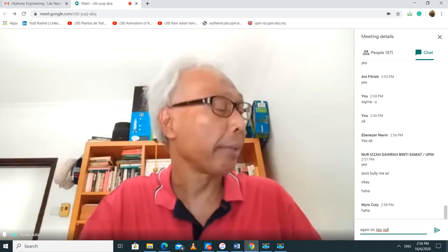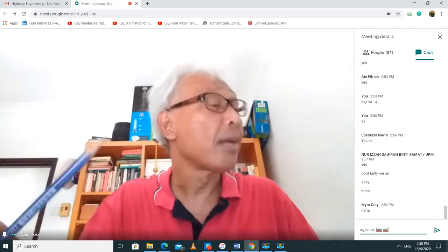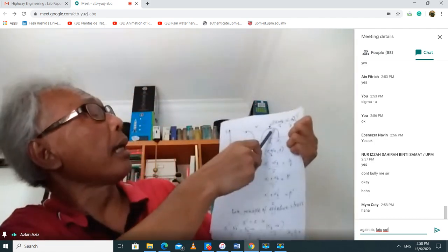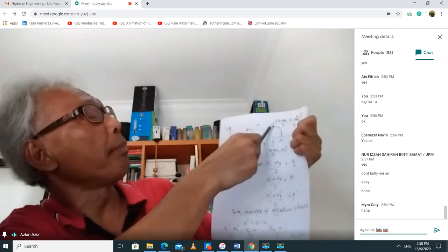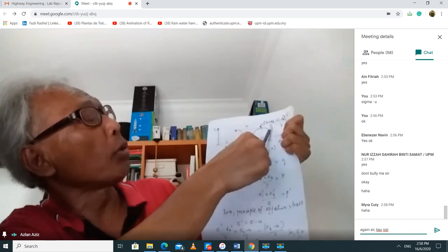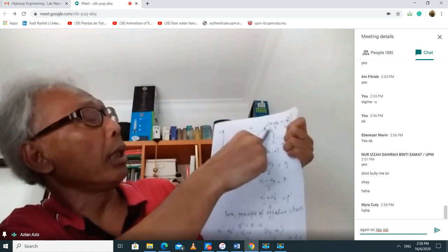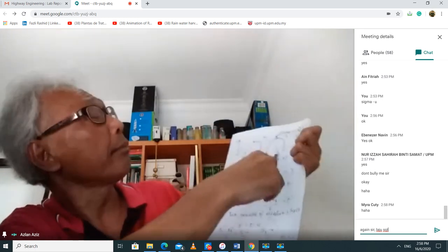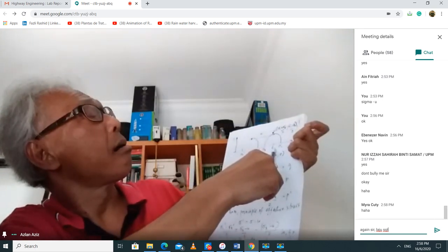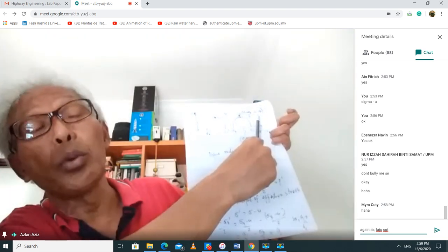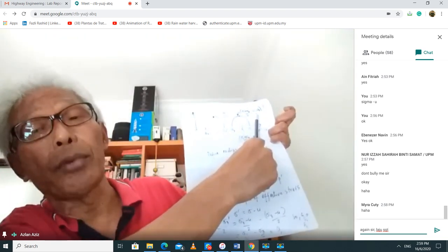Okay, Mira, fine. So then I will be able to say that at the top here it will be the same, right? The coordinate here will be sigma 1 plus sigma 3 divided by 2 for the y coordinate, because it's just the radius of the Mohr circle. And that is just the radius, sigma 1 minus sigma 3 over 2, for the y coordinate.